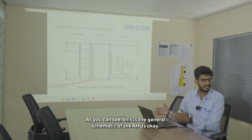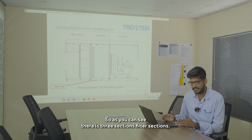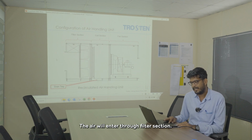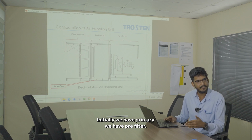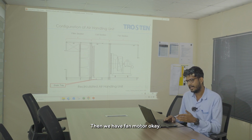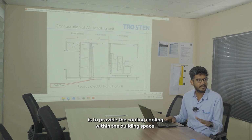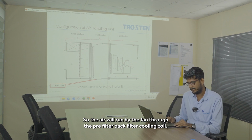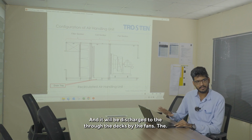As you can see, this is the general schematic of the AHUs. There are 3 sections: the filter section, the cooling coil section, and the fan section. The air will enter through the filter section and get filtered. We have 2 filters: initially a primary pre-filter, then a secondary back filter, then the cooling coil, then the fan motor. The air is drawn by the fan through the pre-filter, back filter, and cooling coil, and discharged through the ducts by the fan.